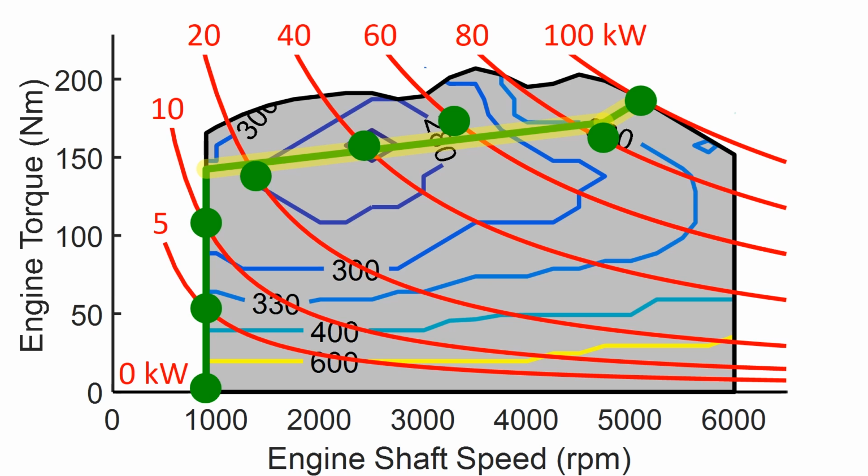These variations are different for different engine designs, but they all have the same general trends, and that is that the peak efficiency is at a high torque, which often increases a little with the engine power. The operating point at the engine's peak power is always at the maximum torque of the engine and a high speed, as that is the only operating point at which that power can be delivered.